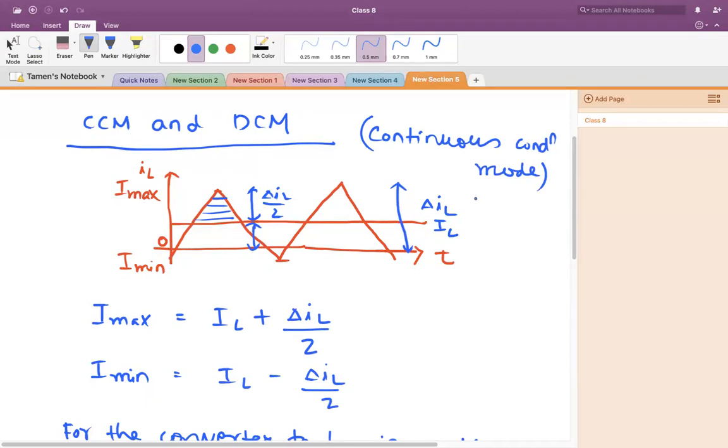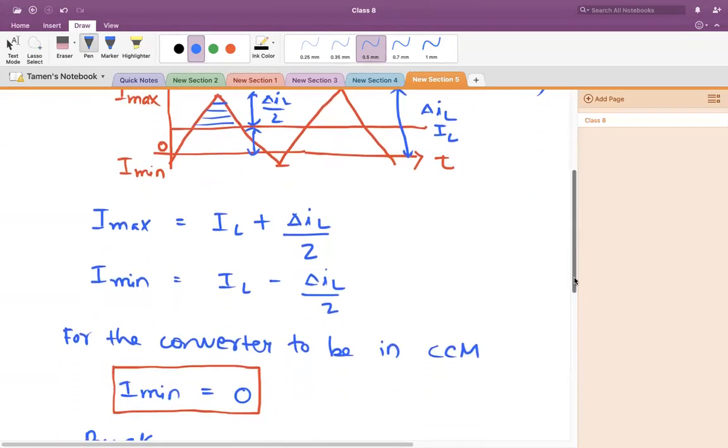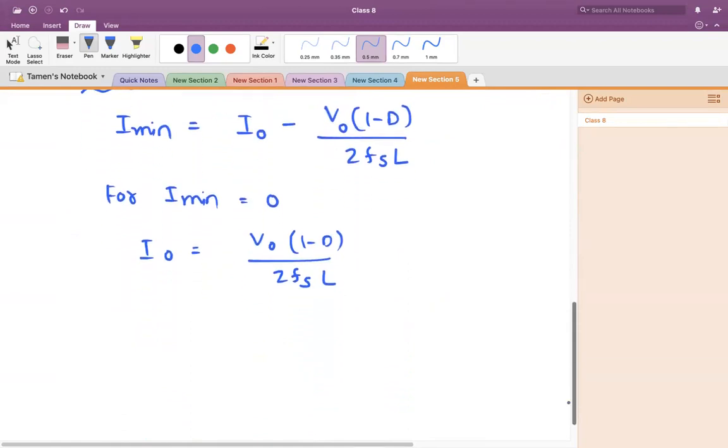Because in order to drive the circuit for a certain kind of application, like we want the EV, like we want the motor, we want the current to remain in a positive mode, basically. It should not change the direction and come to the negative mode. So for that, we require the CCM operation. If the circuit goes to the DCM mode, then you will not get the desired output. There might be some errors you will find.